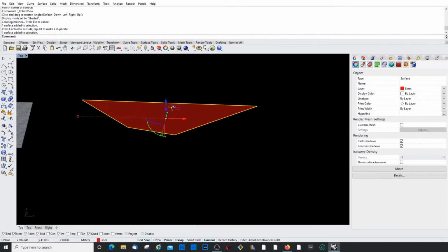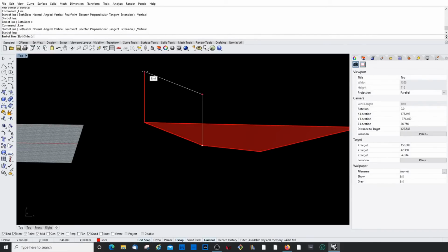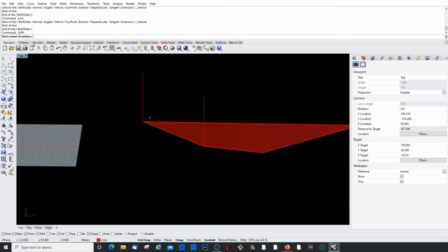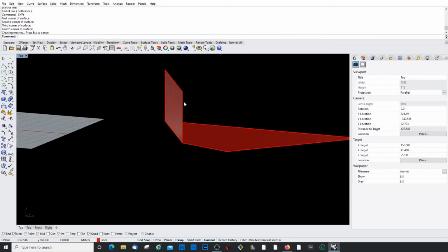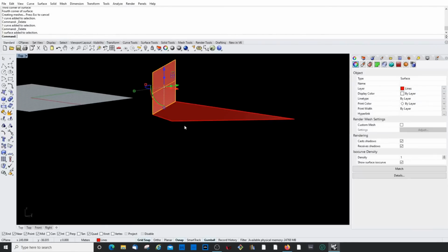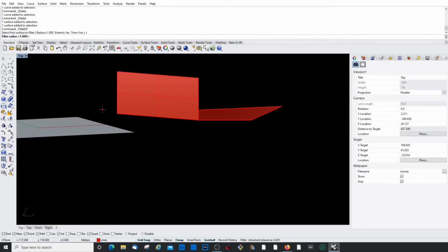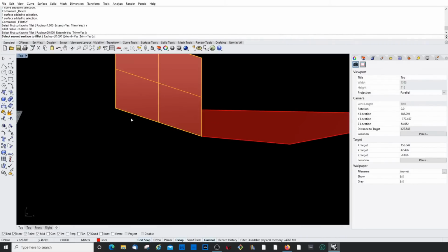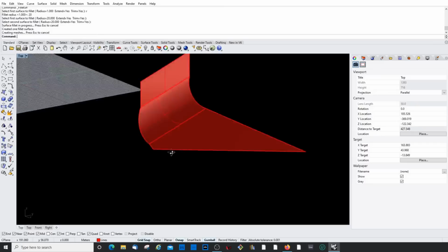Fillet surface, that is, for example, if I have a surface here, I just draw something very quickly. Don't worry if you cannot follow that now, but it's fine. So I will go through that for all these things. So I have two surfaces, and I want to fillet them. You can do that here. You can change the radius again. Fillet radius, let's say 20 meters. Select first surface. So I selected this, and then it asks me to select second surface to fillet. And it does this.